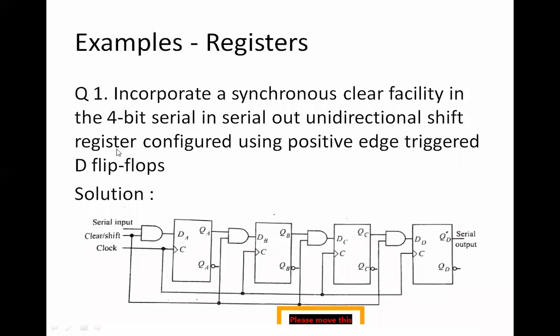So what we will do here is incorporate a synchronous clear facility. How can I incorporate a clear? If all the data are present in the D flip-flop, how can I create this clearing of data in the flip-flop? That's the question. So as usual, we will have these D flip-flops, A, B, C, D.